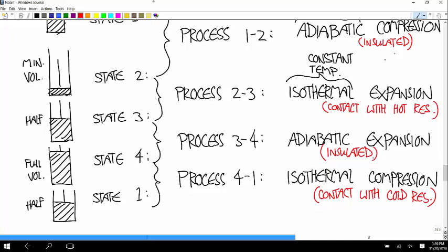That's still a finite temperature difference, but okay, we'll say that that's infinitesimal. How long would you guess it would take for 1,000 kilojoules of energy to transfer in here through heat? A ton of time, because that's just such a small temperature difference. And that's the problem that you're facing with making a truly reversible cycle.